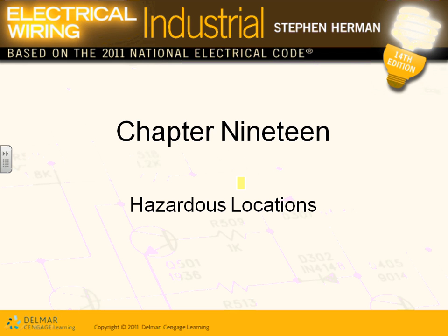And when you design a power system or a lighting system or a low voltage system for these locations, you have to take into consideration what the code requires you to do in these places. The only thing you need to worry about, guys: a branch circuit continues to be a branch circuit, a feeder continues to be a feeder. It's not a big deal. The only thing is the wiring methods that we use in these classified locations.